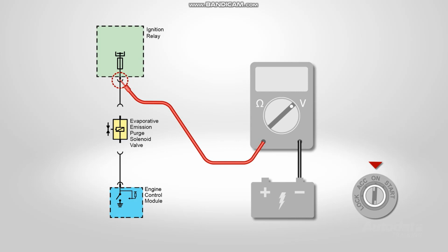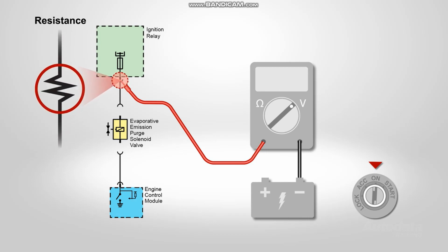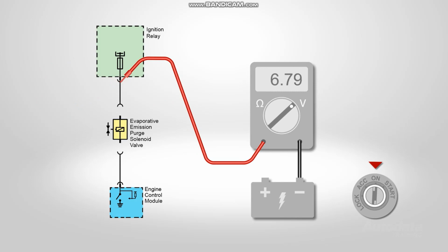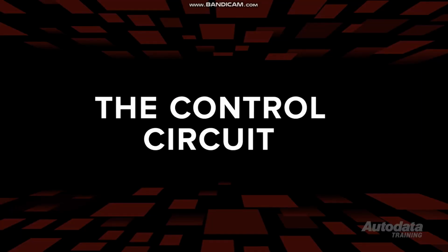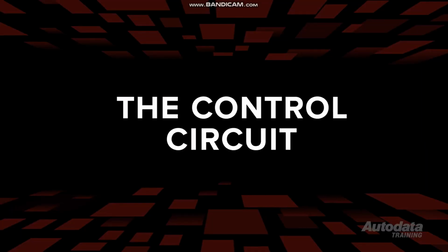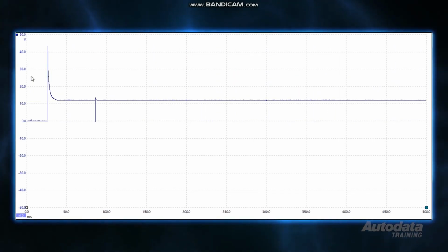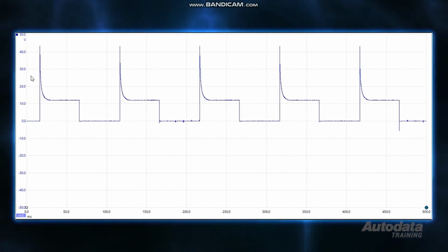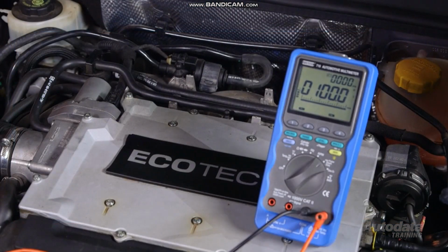A correct voltage reading on one side of the connector with an incorrect reading on the other will indicate an excess resistance in the connector. An incorrect voltage reading before the connector indicates excess circuit resistance between that connector and the fuse. Because the ECM controls the evap solenoid with a PWM ground path, it is necessary to check this control with an oscilloscope or a multimeter.